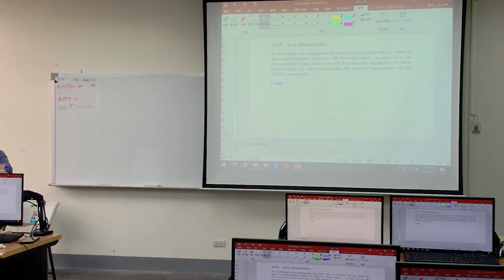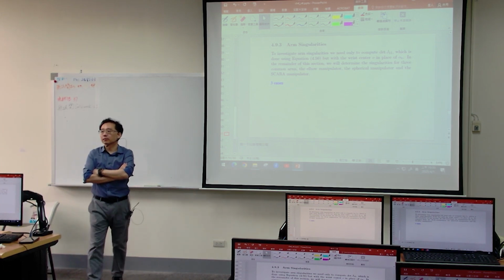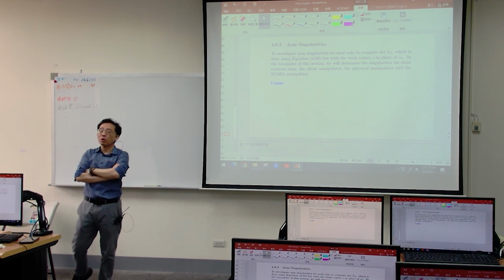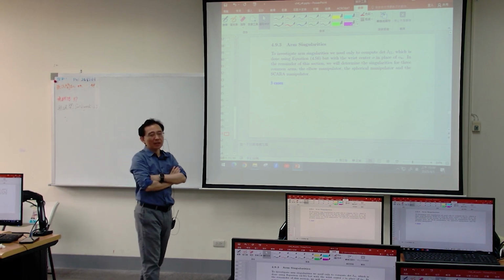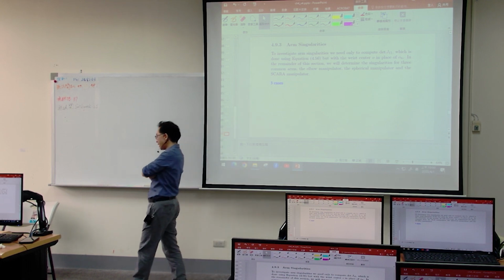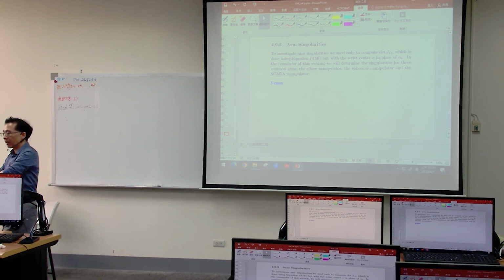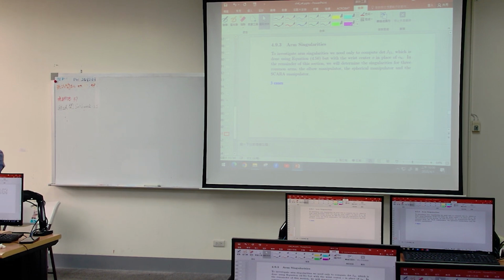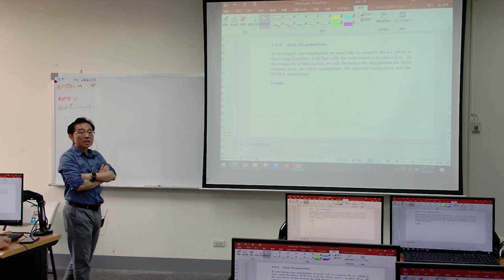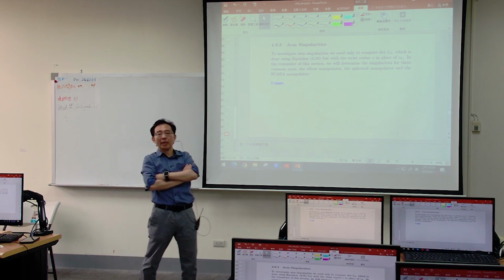Let me continue with the arm singularity. After we discuss the final end, that's why we call it end-effector. The wrist is wrist, but anything attached to the wrist section is called the end-effector. In this session, we finished the wrist. For the arm singularity, we only need to compute J11. If J11 equals 0, it means a singularity shows up, and it must show in the arm section.